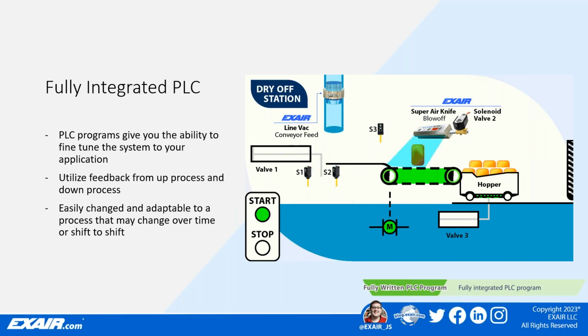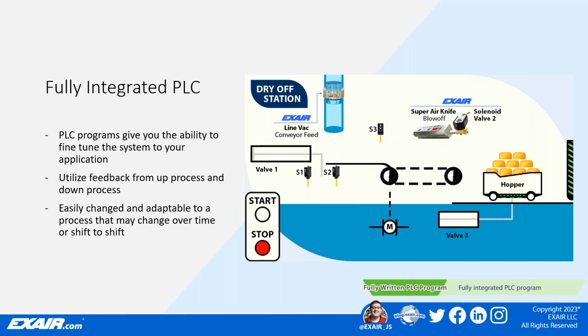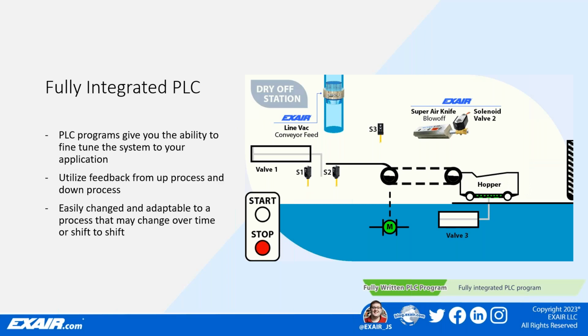Or downstream, say they only use water to cool a part if its temperature reaches a set point. There would be no reason to turn the air on for every product, just the products that have been cooled by water, to dry them off. A PLC can keep track of that data and control a solenoid valve to open and close based off of the wet part.